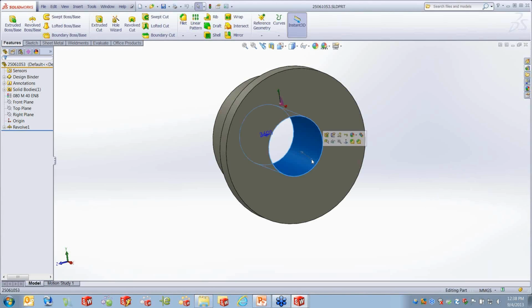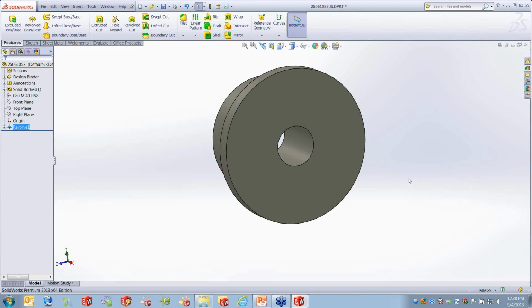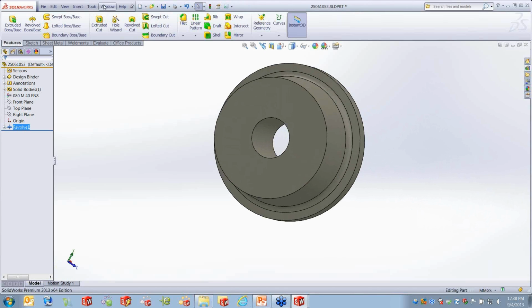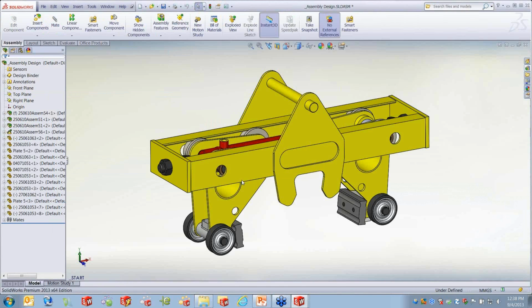Now, most times when I see someone using that, they do the Save As Copy, and then they start to modify what's here, because they think that they've just made a copy, so they're not working on the original. So they made a change in the design, and now when they jump back to the assembly, guess what? The assembly's changed. Well, I made a copy.